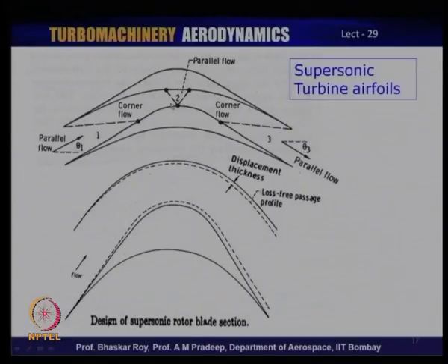So, typically supersonic blades like these would have supersonic flow through the entire blade passage. It is coming in supersonically, going out supersonically. Inside of the passage, it would have a continuous train of shocks or fans. It is most likely that the flow would be going through the entire blade supersonically. One of the oldest methods of designing supersonic turbine blades is not to have any acceleration or deceleration inside the passage, but a constant supersonic Mach number blade. That was the earliest design that people have used for supersonic turbines.